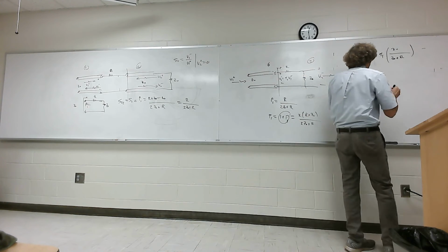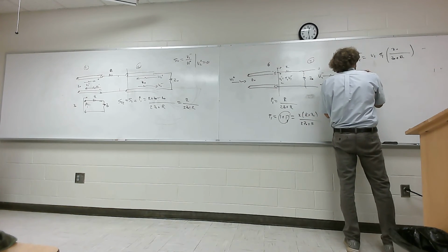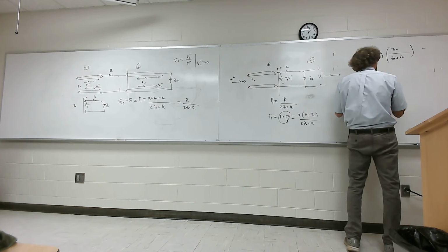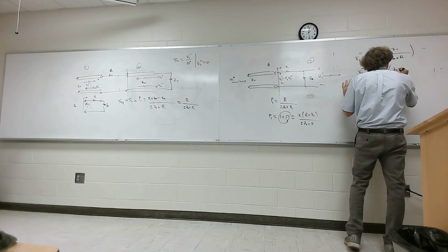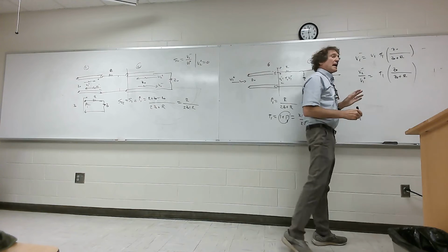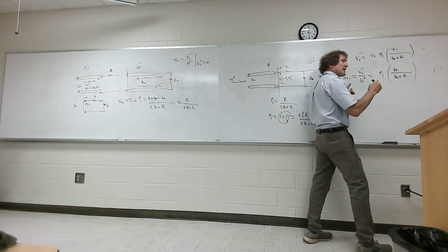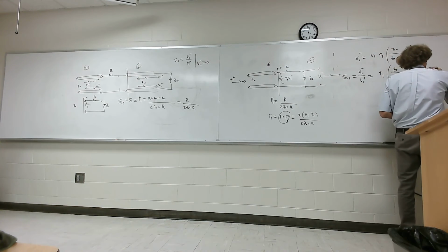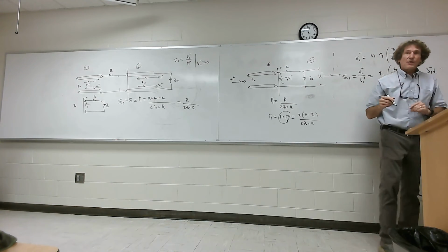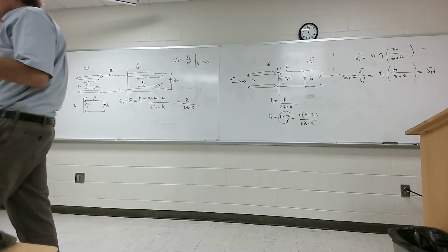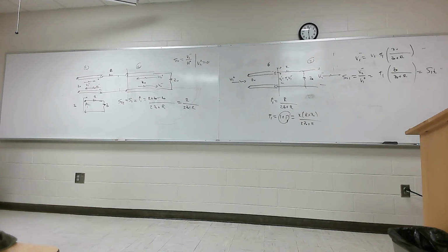So that means, really, when I take a look at V2 minus over V1 plus, it's just equal to the transmission coefficient of port 1 times Z0 over Z0 plus R. And that would be S21, and in our case, because of arguments of symmetry, it would be S12. Y'all follow me? They will be the same. If you have one, you have the other. Does that make sense?